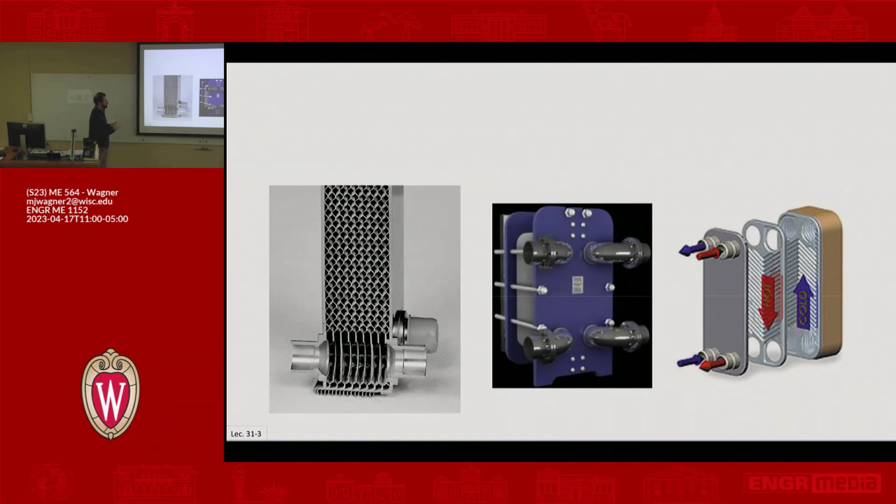So if you're trying to get good heat transfer, the limiting thing there is the amount of surface area that's available for convection. So what heat exchangers will typically do is they will add a ton of surface area to take advantage of the fact that heat conducts really well through the metal, can spread out, and then have more surface area available for convection. So you're driving down the resistance on the convection side.